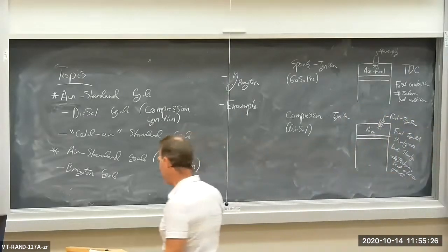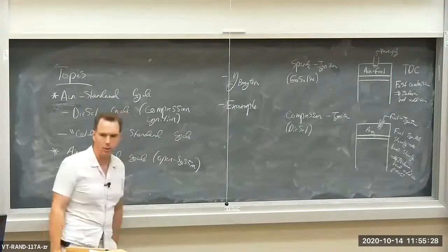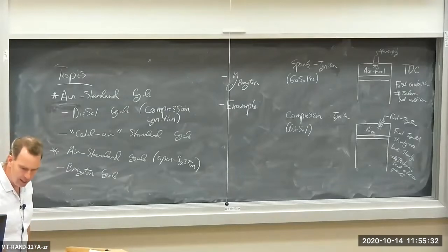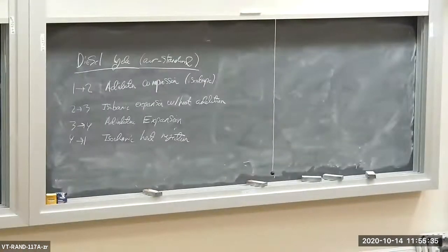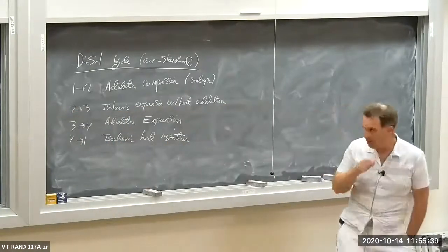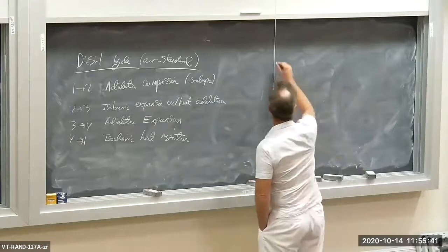Isobaric, constant pressure heat addition process. Everything else is the same as the Otto cycle. It's just that we're changing the heat addition process. So let's have a look here at the diesel cycle, the air standard diesel cycle. Let's put up the TS and the PV diagram here.